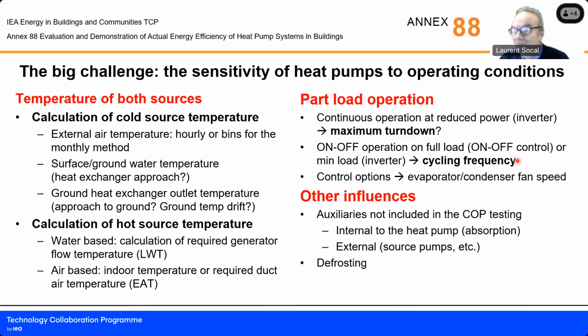And one thing more, it depends also not only on the part load, but also on the cycling frequency. And this is, again, a complicated interaction of your heat pump with the surroundings. And I don't think many calculation methods go into these details, but they are important, as you have seen in the first slides about the previous part, where you saw the difference of testing a heat pump at constant operating condition or in on-off operating condition with the same temperature of the source and the sink.